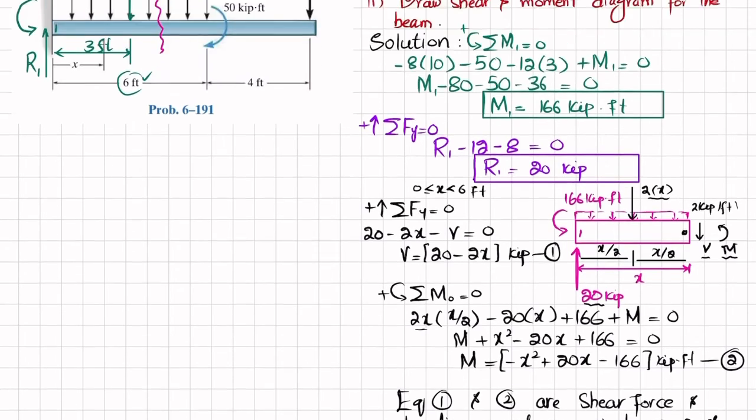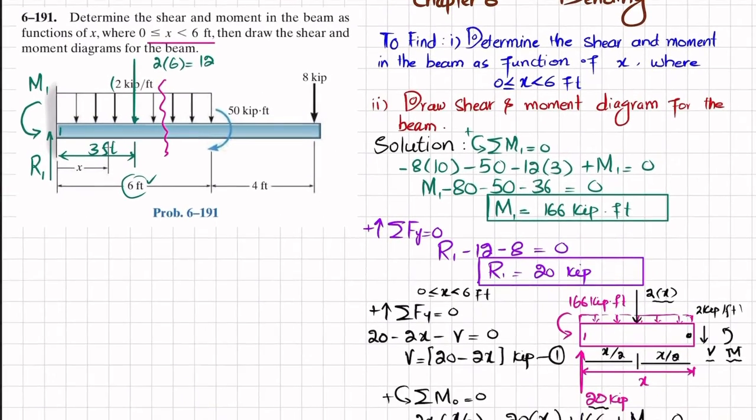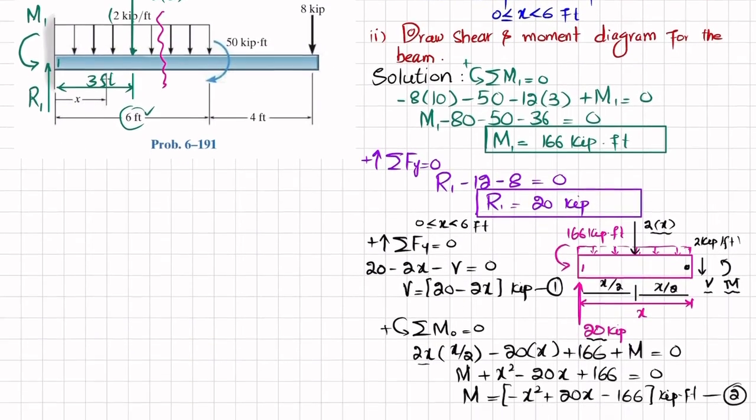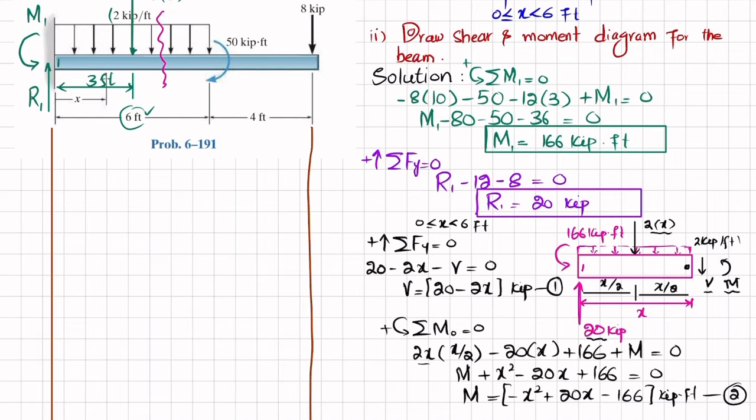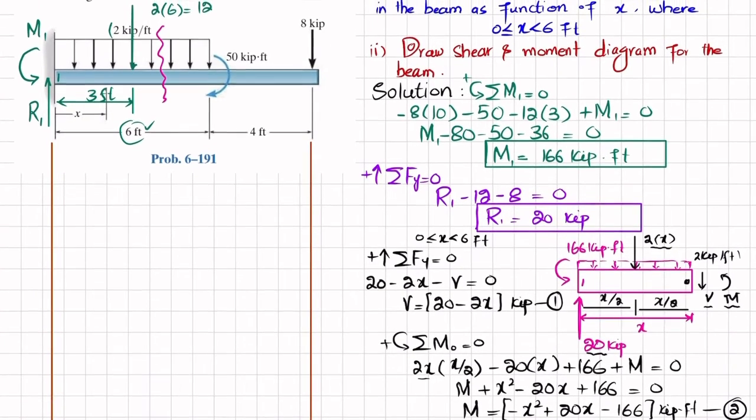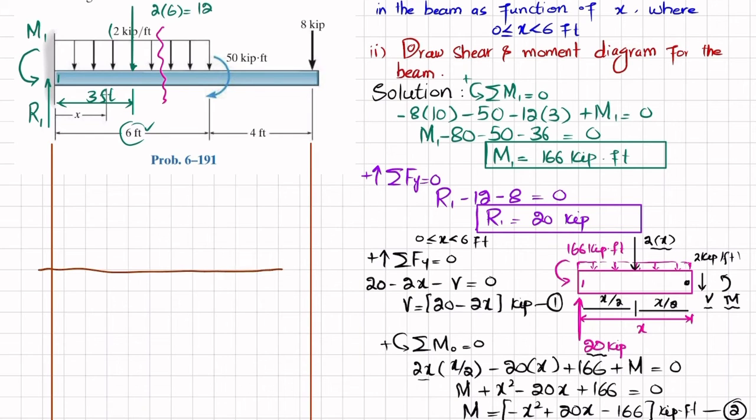Now we'll move toward drawing the shear force and bending moment diagram. What we will do is take a vertical line from the end of this beam, and first we will draw the shear force. For shear force I will take a horizontal line to show length x in feet, and on the y-axis we have shear force and the unit will be kips. Clear? Let one division be equal to 5, so 5, 10, 15, and 20, and similarly downward, that is minus.